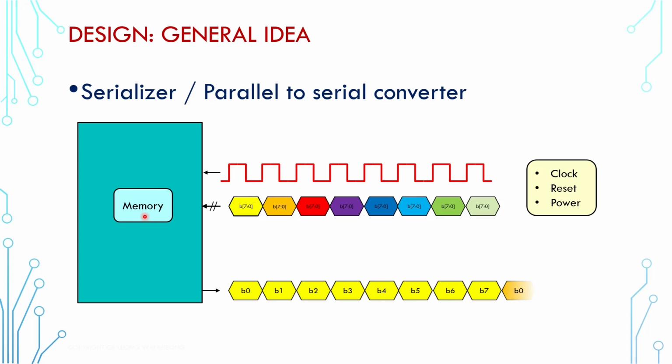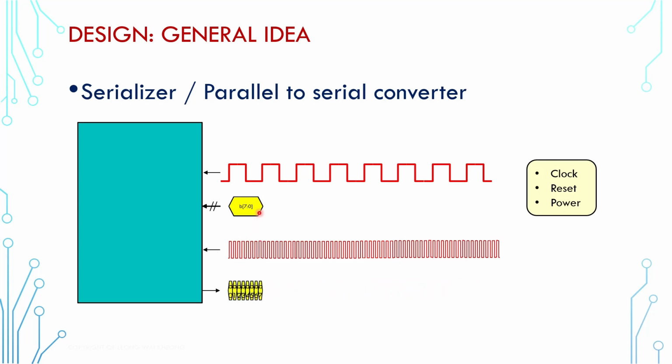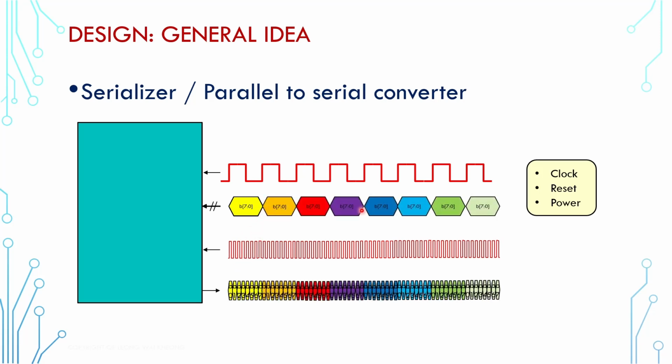For example, how many pending data can the design store? What happens if the memory is full? Now let's look at another possibility. If the design operates at 2 clocks, where the second clock is 8 times faster, then it can convert input data back to back. And now it sounds nice, but again there are complications.